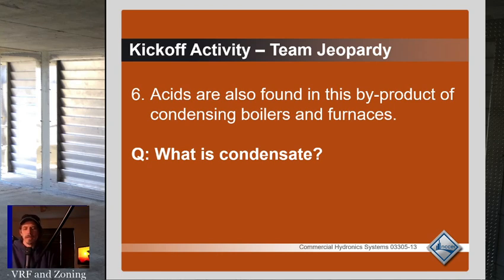The condensate gets created in the flue, and the condensate is corrosive. Alright, the condensate is not that corrosive. I think it's overplayed a little bit how corrosive flue condensate is, but it is corrosive, which is why you see everybody doing neutralizers now. In commercial, it's required by code at this point. It's not really required by residential, but it is to the point where neutralizers are required in commercial.